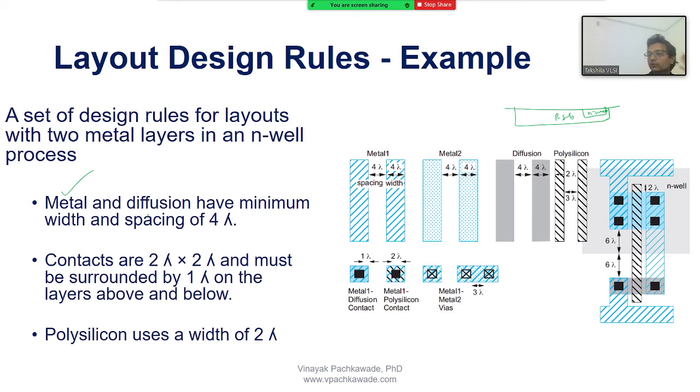So what are your design rules? First rule, you need to adhere to and follow all these rules while drawing your layout. Of course, the tool will do it for you. The tool will follow all these rules, but still there will be some instances where you have to interfere, because you are the engineers of that physical design. So at some instances you have to manually adjust things.